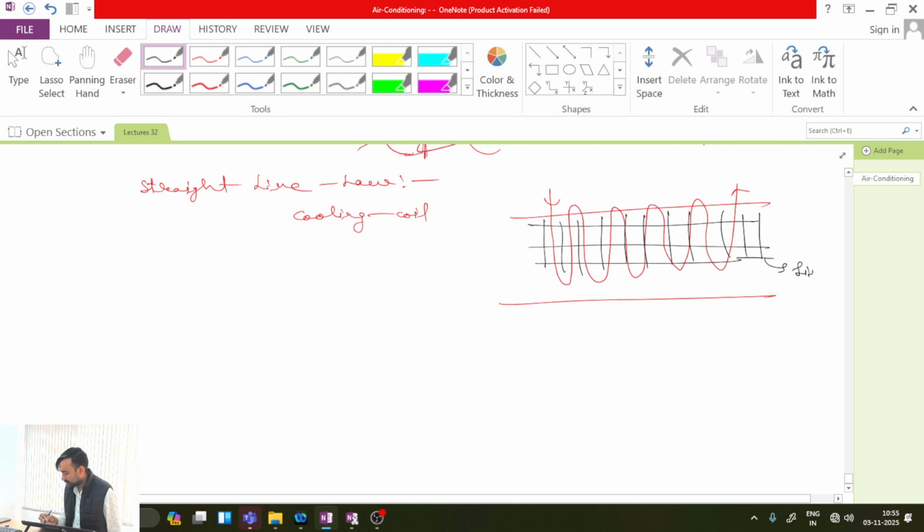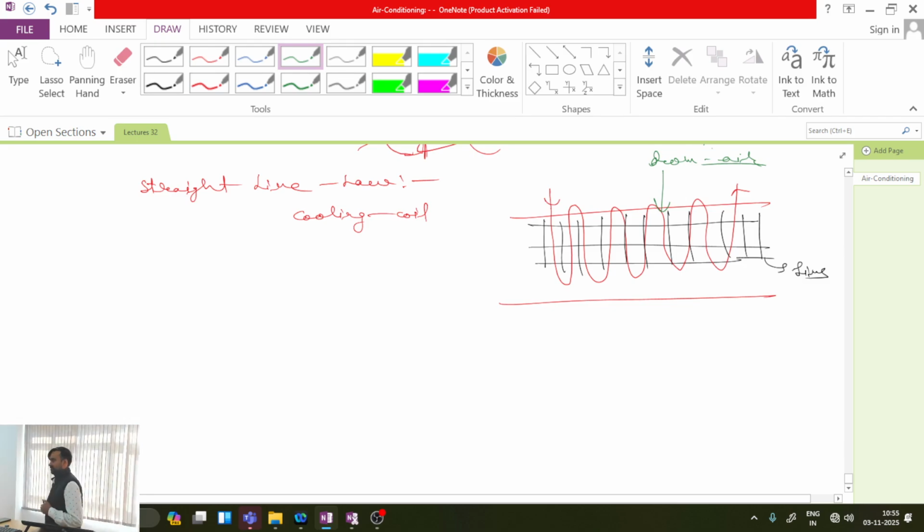These are fins, and then in the cross flow direction room air is circulated over this, and when it moves over this coil, it leads to different processes. Okay, cooling and humidification, heating and humidification, sensible cooling, pure humidification, depending upon the type of process we want to achieve. Is this point clear? Does anyone have any doubt about this?